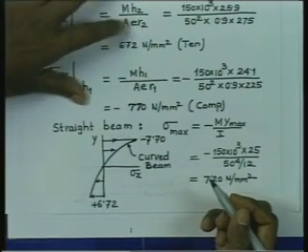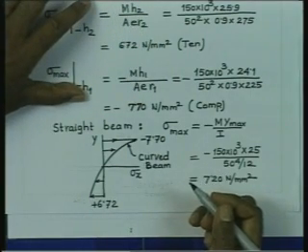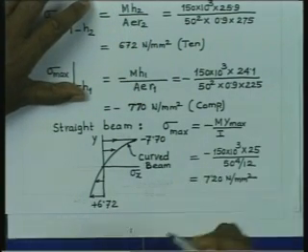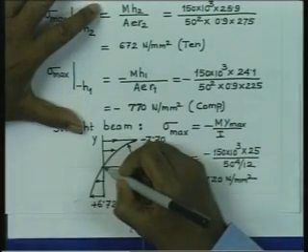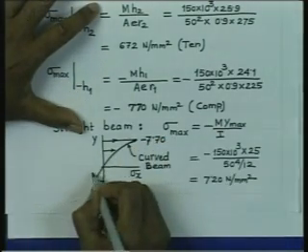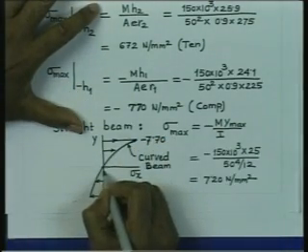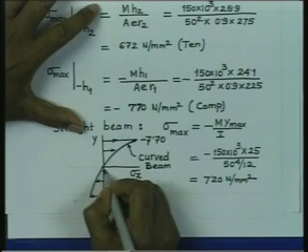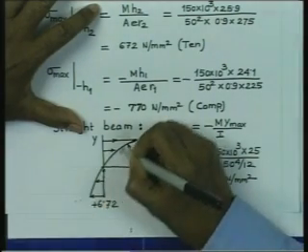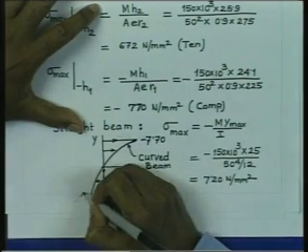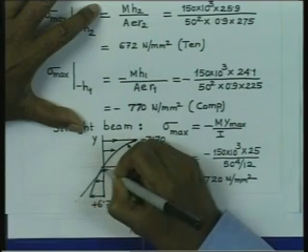On the other hand, if we show the stresses given by the straight beam formula, it has a variation which is straight. So, this will pass through the centroid of the cross section, and the variation is straight. So, we will have variation of this type.